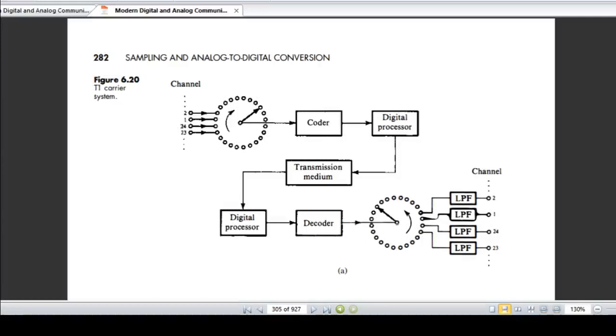Next, the signal is transmitted over a transmission medium, that will be a wideband coaxial cable. During the transmission, periodically after every 6,000 feet, the T1 carrier signal is regenerated by an amplifier, which is called a regenerative repeater.